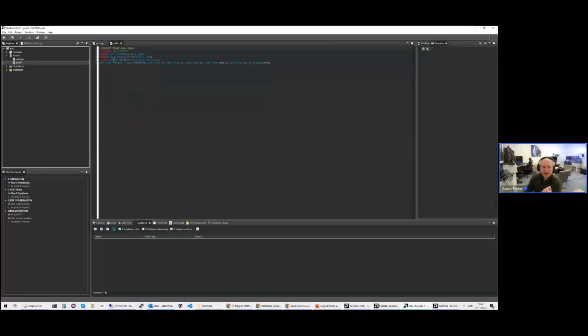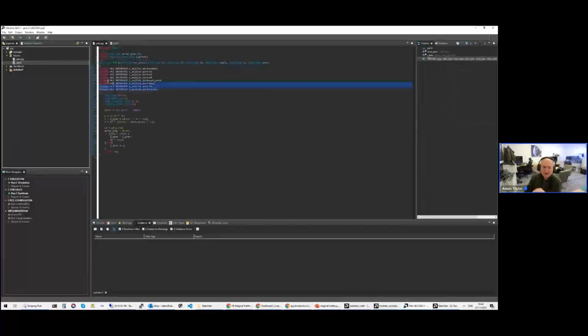In our header file, I've defined the AP integer types that I want. For example, I've defined some 16-bit ones, some 32-bit ones, and some 48-bit ones. Again, you've got to keep track of the growth of the result, but it gives us a really simple, really easy, really flexible way to be able to do maths. And although we're not here to talk about that, this element gives us the ability to easily change the interfaces on the FPGA as well. So we can change the interfaces from, for example, logic to AXI to block RAM to FIFO. So there's a range of applications that we can do that with.